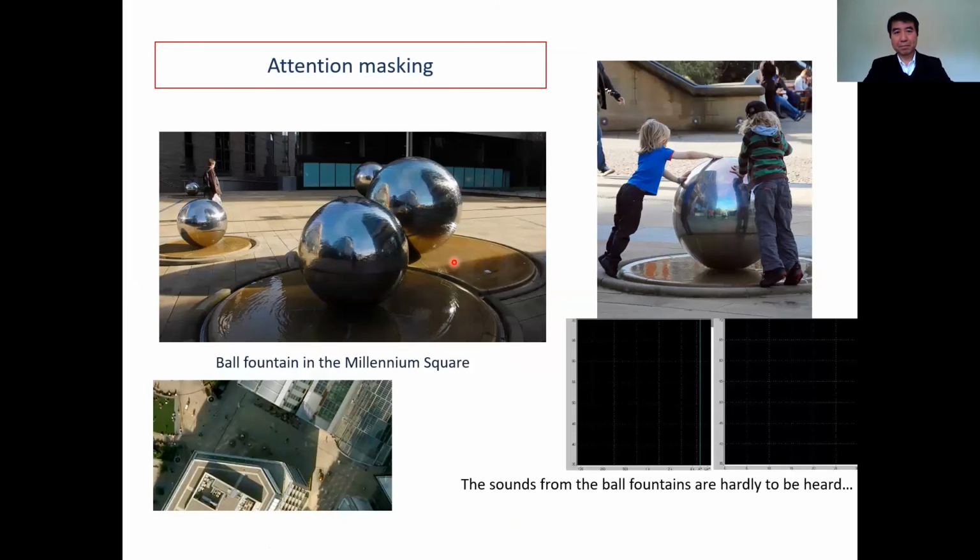And that's another example on that gold route. It's quite different. That's the spectrum. You can see it's very, very low. Actually, there's almost no sound. But because the water is running, people's attention is attracted by this water feature. So different from what I said previously, energetic masking, where you use sound to mask another sound, this is attention masking. You don't need a loud sound, because you attract people's attention even with a very low sound level. So people pay less attention to other unwanted sound and pay more attention to this sound. So that's another very useful treatment for soundscape design.